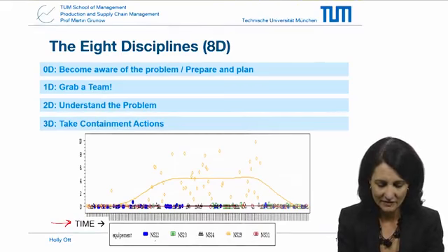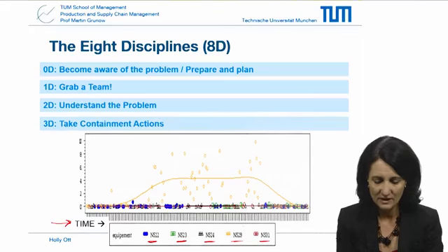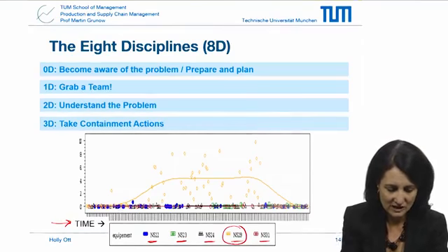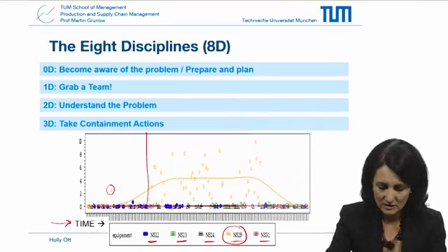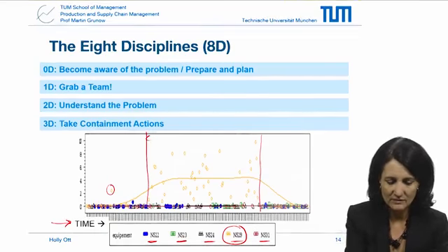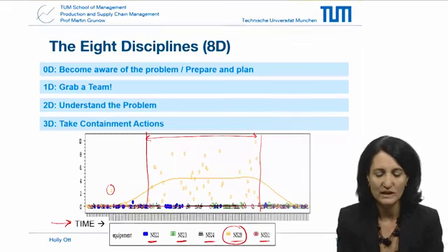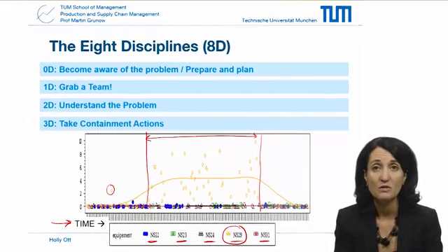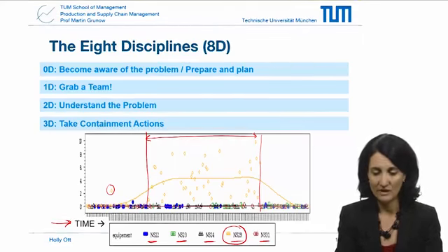And what we see is we have 5 different machines, NS22, 23, 24, 29, and 31. And here we see 29 with the orange diamonds. And what you can see is starting at a certain point of time, there's one here, then it seems to be okay. But basically, from right about here to here, this certain time period, everything that was processed on NS29 is giving a crazy signature. It's not where it's supposed to be. So here we know any parts that are processed on NS29 in that period are likely to have a problem.